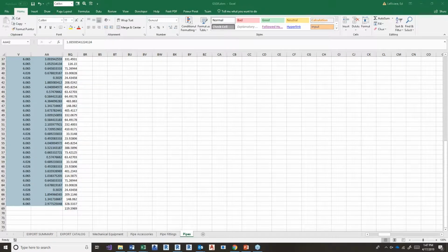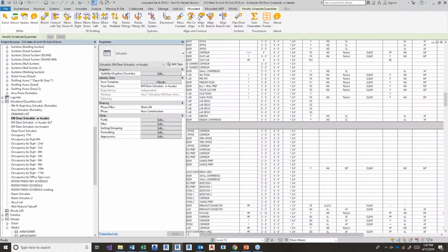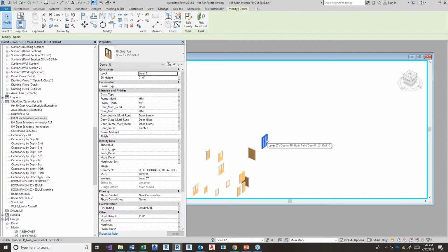Oh, so is it possible to delete the mark value if it's not needed? So Revit requires a mark value for most families of an instance type. So the mark value seems to be a function of the element category. In a door, architects use the mark value to indicate the room number, right?